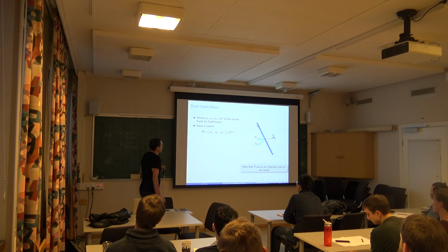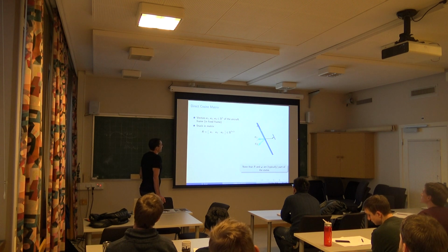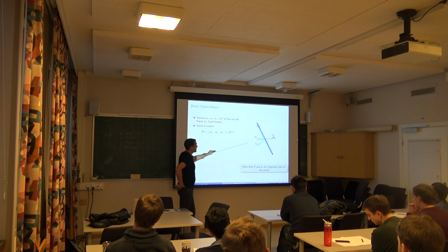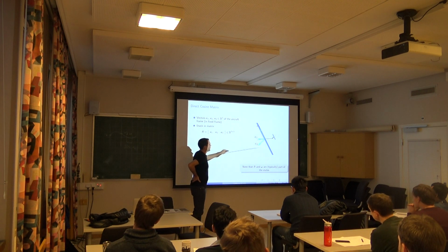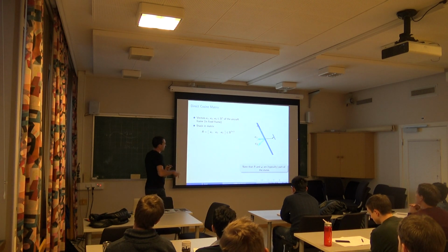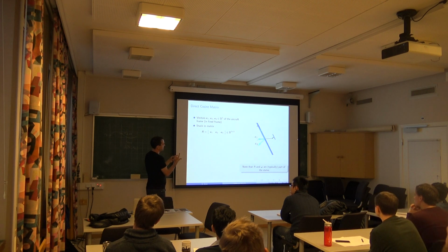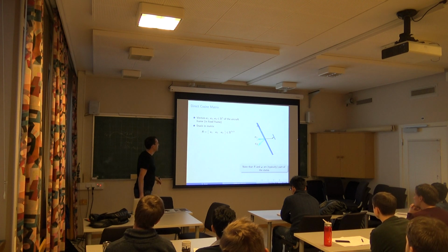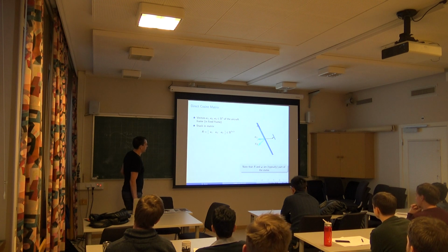It solves a lot of problems in modeling these systems. And I'll explain a bit later, but we tend to use the full rotation matrix for representing rotations when we do optimal control. And in that sense, essentially, you take the 3 leading vectors of the frame attached to your aircraft, and you basically express these vectors in the Earth reference frame, and you get your rotation matrix made of 9 numbers. You can put them in a 3x3 matrix. You could also put them as a list of 9 numbers.